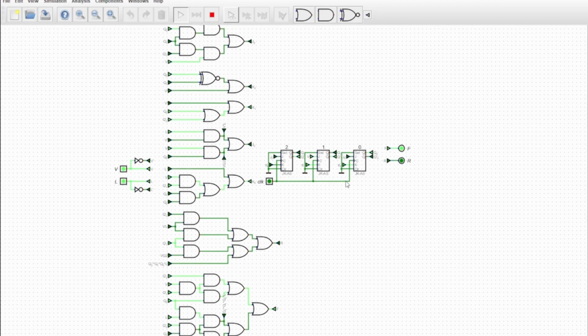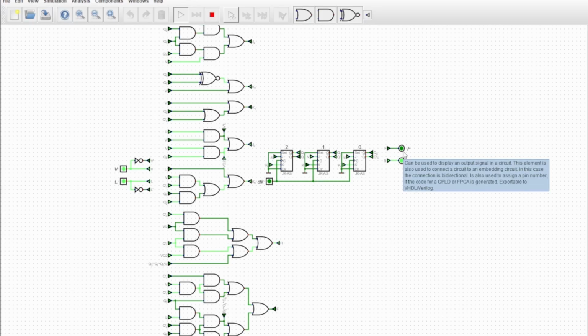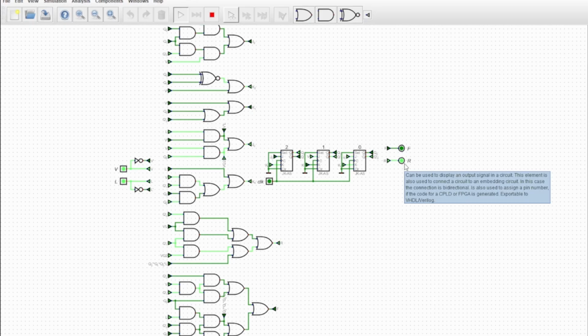As you can see here, S2 happens where we have the 1, 0, with F being on and R being off. And here is where the clock states matter. So once we have F on, F will be asserted for only 2 clocks. So as you can see, F turns off after 2 clocks. And once F turns off, instead of turning off the entire circuit, we have that for at least 1 clock cycle. So we're in S3 now. So we have that 1 clock cycle where S3 acts like S1.